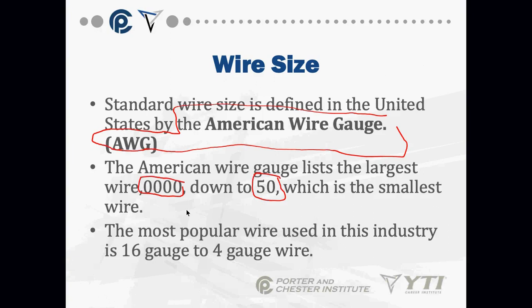What do we use for thermostat wire? I think I've given you this number already once. What's our gauge? I'm guessing like 24 gauge. Well, the true thermostat wire is 18 gauge. It comes with 18 slash another number, like 6. So if I have 18 slash 6, that tells me my thermostat cable has 6 strands of 18 gauge wire, 6 individual wires that are 18 gauge.